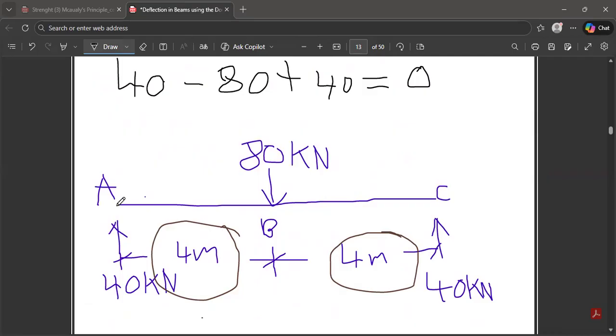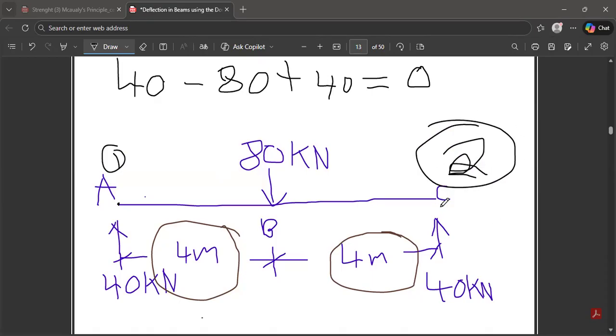So if you come to boundary condition 2, it is the other end of the beam. So this is boundary condition 1, and this is your boundary condition 2, just at the support of the beam. If you pick boundary condition 2 over here, your value of X is what? 8. That is the whole span. It becomes 8. And the Y is still what? 0. So always for the boundary condition, your Y will be 0. At a support, your Y will always be 0. For the X, the span will tell, depending on where you are standing. Exactly.